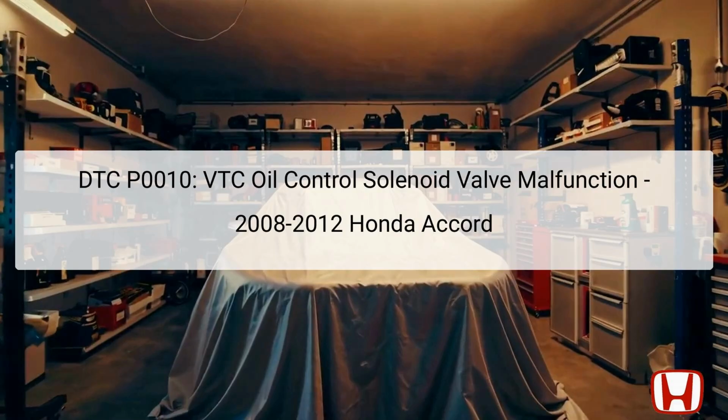Typically located in the cylinder head, the VTC oil control solenoid can be affected by various external factors, such as oil quality, electrical connections, and internal wear. Diagnosing issues related to this solenoid involves a systematic approach to confirm the malfunction and rectify it efficiently. Proper troubleshooting is crucial to restore functionality and ensure the vehicle operates smoothly.